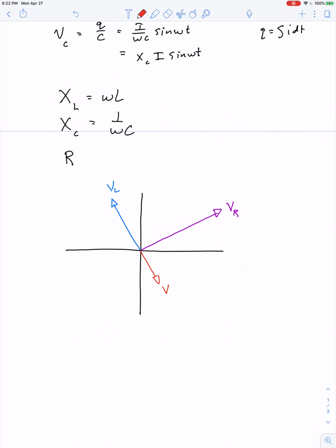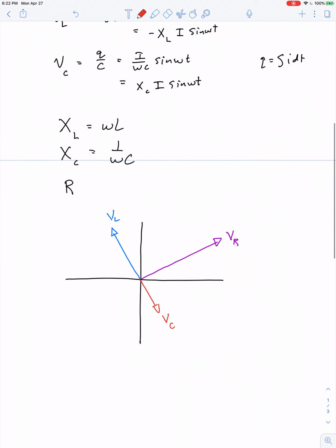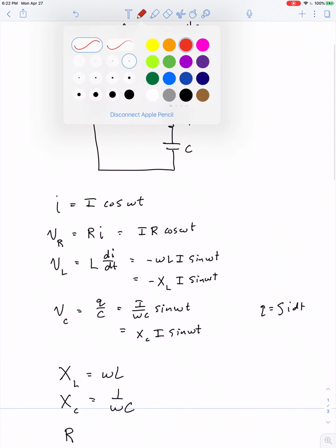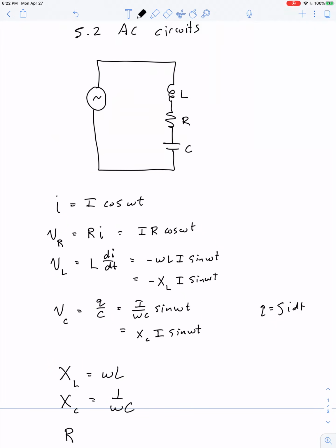So in this phasor diagram, I'm consistent with the one from our last video lesson, where this must be a circuit where the frequency of the generator is slightly higher than the resonant frequency. So we say omega is greater than omega naught. Omega naught represents resonant frequency.